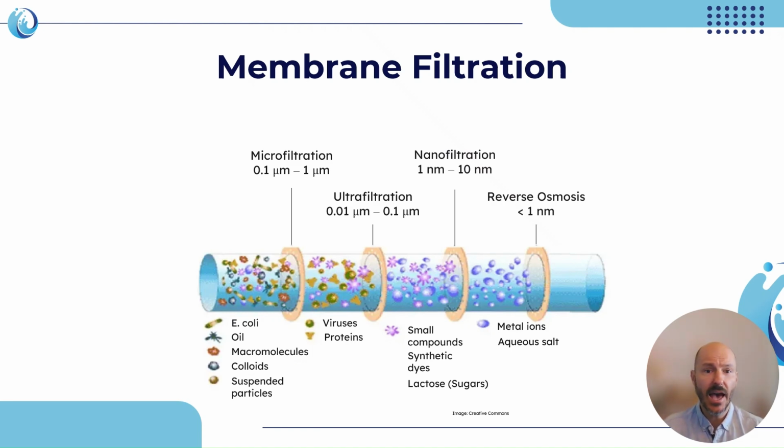Microfiltration membranes have the largest pores, typically ranging from 0.1 to 1 micrometer. They effectively remove suspended solids, algae, and most bacteria, but allow dissolved organic compounds, nutrients, and salts to pass. Microfiltration is primarily a physical treatment process, providing excellent clarification and pathogen reduction when combined with disinfection.